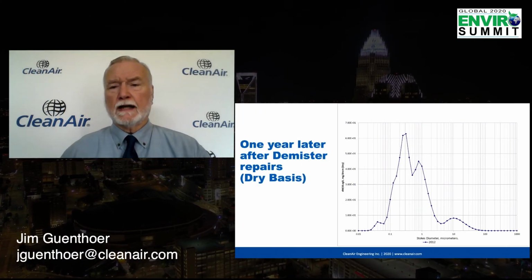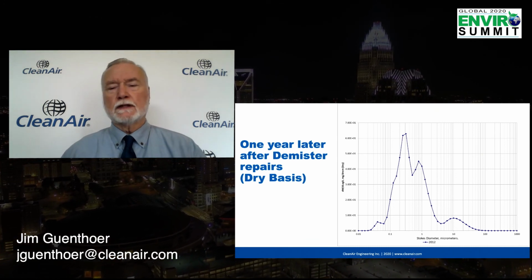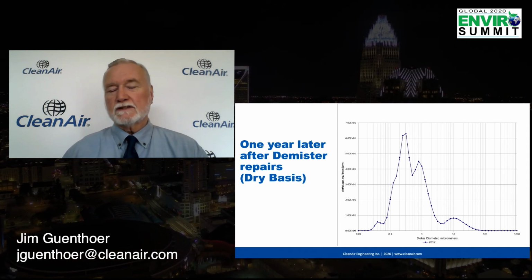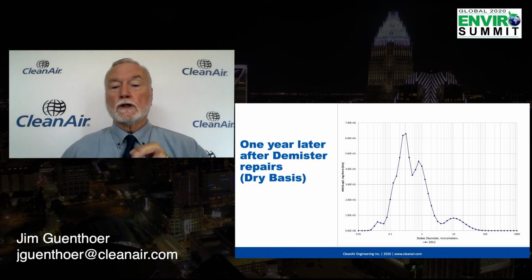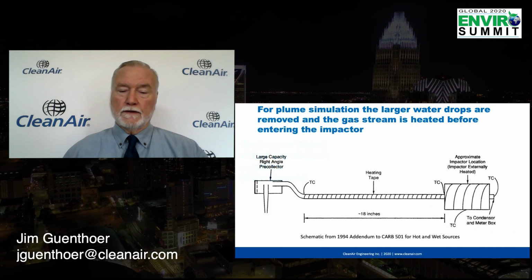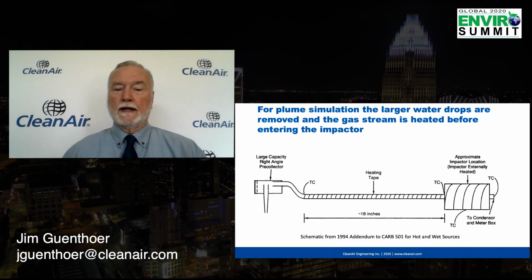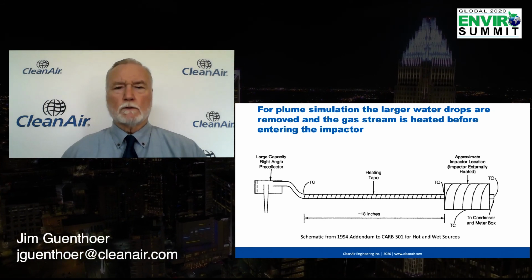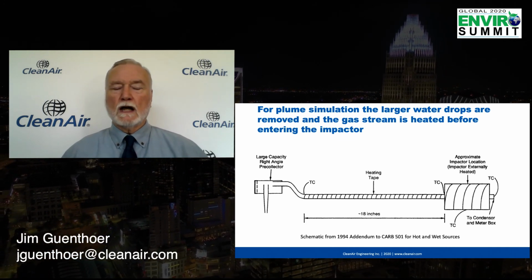It has a lot of varied applications, and in certain cases, like I said, this is dealing with particulate matter, so it has to be a solid or a liquid droplet. Now, if we're looking at plume simulation, this was a variant of when they created CARB 501. California said, what happens if it's a wet stack? Same thing everybody says, what happens if it's a wet stack? So here they used a larger pre-cutter, as you notice on the left, that took out 20, 50 micron drops and larger,